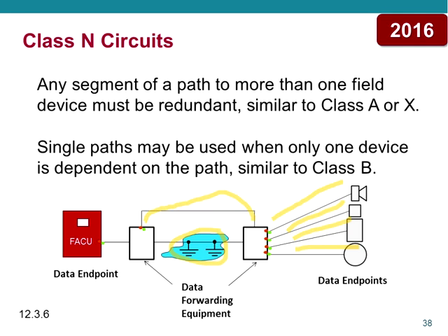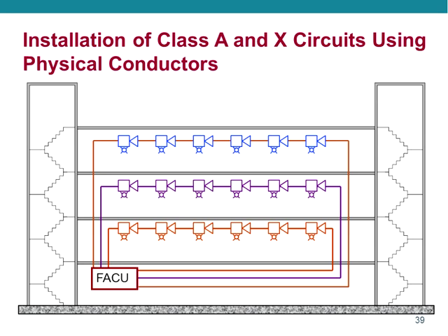You have to understand that these are basically galvanically isolated, and they don't have any monitoring for integrity. They don't report ground faults, but when they have a ground fault, it's basically isolated, so you need to provide a secondary path. And the chances of a ground fault are no greater than on any other circuit. So again, the risk is acceptable to the committee, and we added a whole section here on Class N.